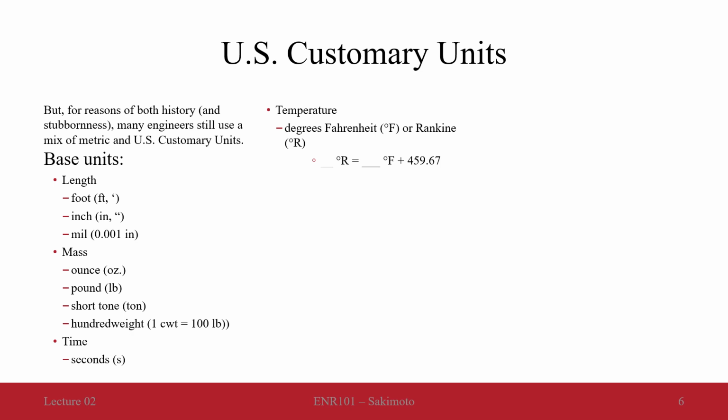Of course, here in the US, we commonly will measure things in terms of degrees Fahrenheit, but to solve the similar negative temperature problem as we had with degrees Celsius, engineering in particular uses this degrees Rankine notation, which is degrees Fahrenheit plus 459.67, again trying to get rid of any negative temperatures by adding and shifting all the values up.